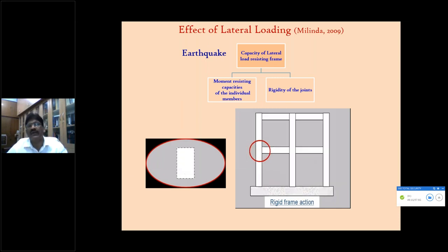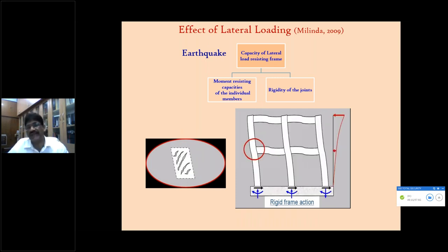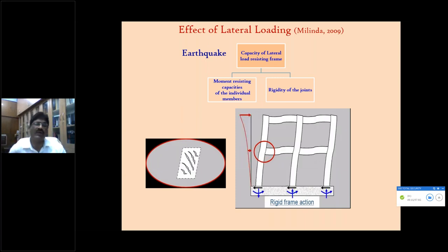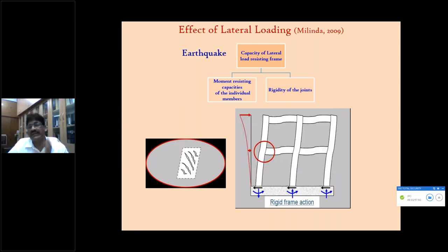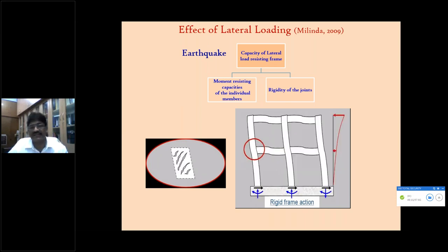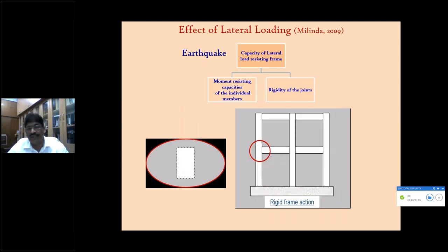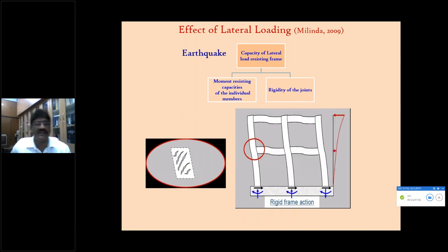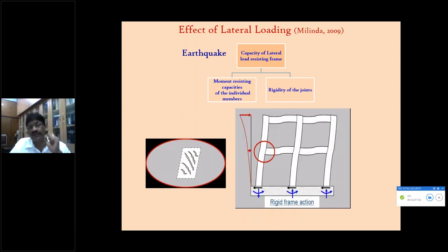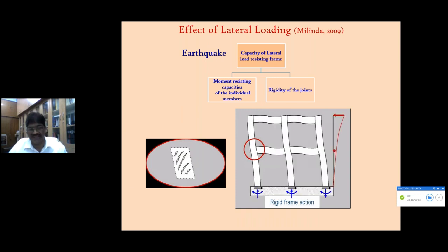Of course this is a bare frame with columns, beams, and the intersection of the beams and columns. And we have the slabs and other systems, right? So this is the typical one. One can understand the deformation of the building, because if you want to design a structural system, you should understand how it is going to deform physically, and accordingly which face is in tension, which face is in compression, and hence. Okay, this is a typical case. The intention is to understand the forces developed in the joint region.